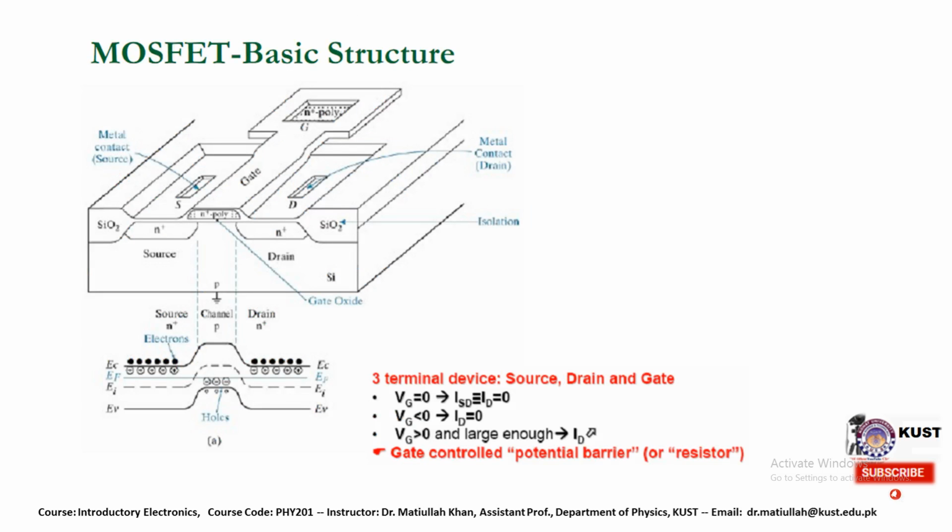This is the other, more detailed structure of the MOSFET, and this is actually the motion of the charge carriers which are responsible for the channel. Here we have the source, and again this is an n-channel MOSFET. This is the source and this is the drain, and this is the SiO2 layer. This is actually the gate, if we take a side look. It is just above the channel, so from the upper side it can control the width of this channel.